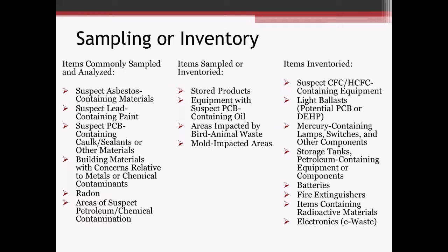Radon. Especially if you're renovating a building, that's a good time to test for radon if it hasn't been done already. That way you can decide, okay, do I need to do something in the lowest level, the basement level, to attack radon and make sure it's not going to be a continued problem if it does test high.